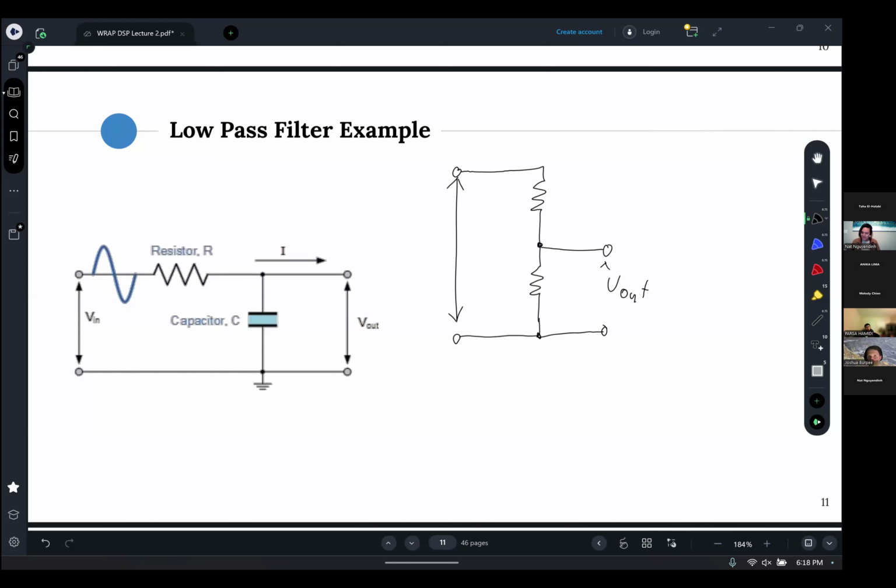All right, this should be a very quick audience participation. What did I just draw here? Voltage divider. Perfect. Thank you. And then does anyone know the equation for the voltage divider? V_O would just be the ratio of R2 over the total resistance times V_in. Yep.